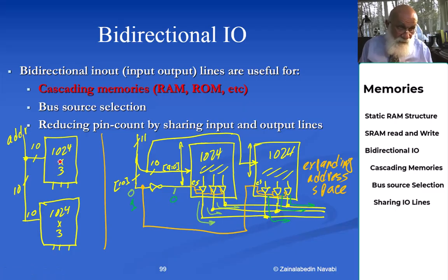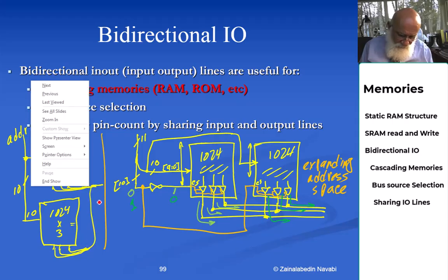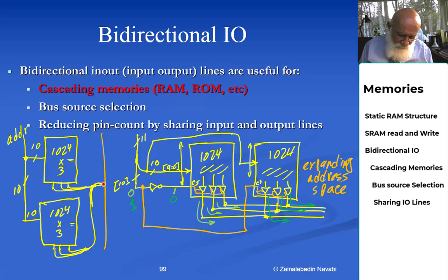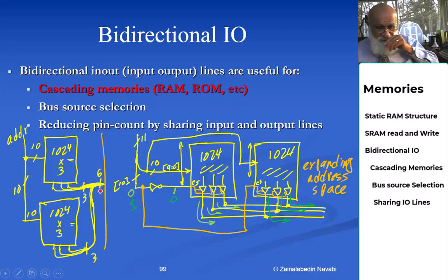And then when you have a certain address, you will be selecting a word from here, the same word in the same position from the lower memory. And then this becomes 3 of your bits. This becomes the other 3 bits. And then, in a way, you are merging these. Okay, so 3 bits here, 3 bits here, and then you have a total of 6 bits.